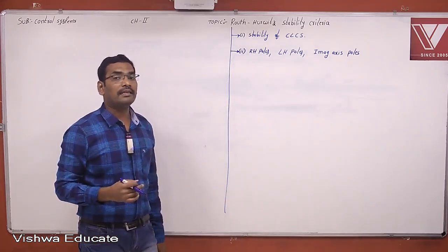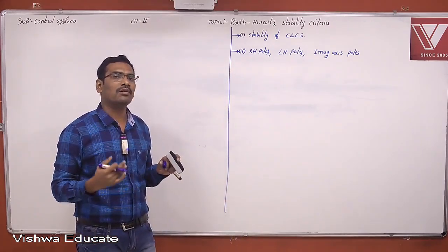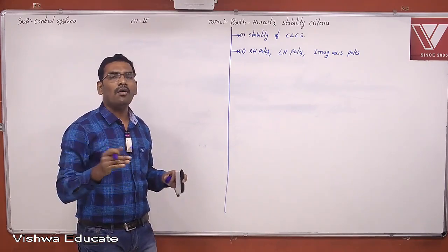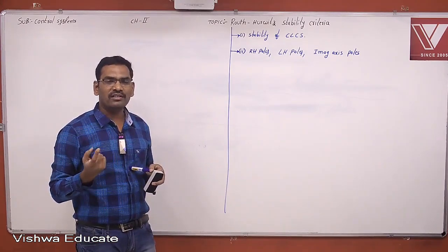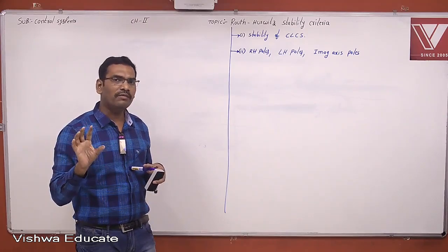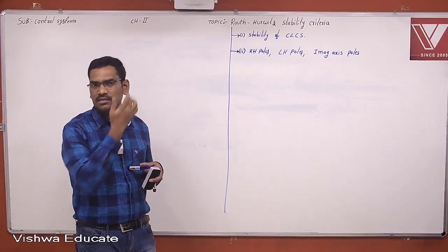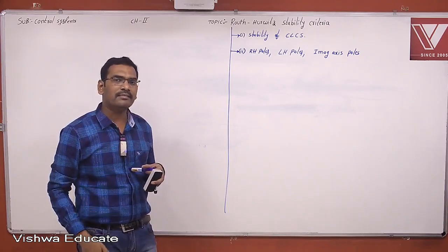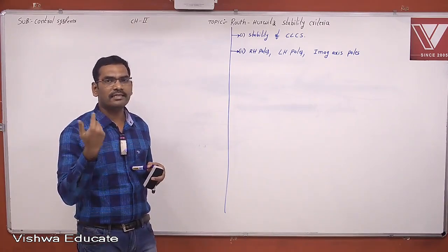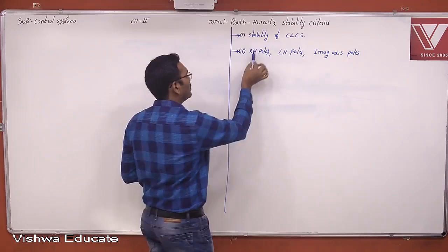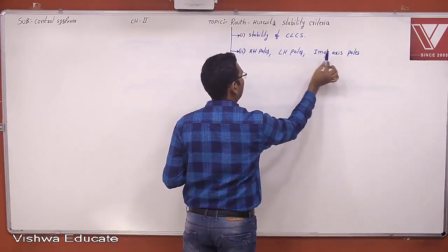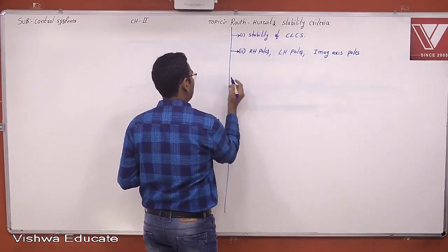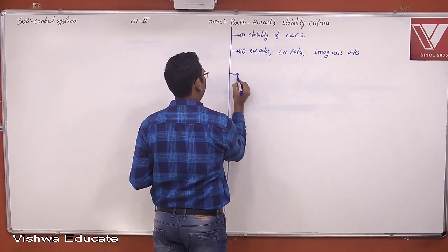Now the RH criteria finds the number of poles on the right hand side, left hand side, and imaginary axis. Sir, if you know how many poles are on the right hand side, you have confidence, and the answer is very simple. If even one pole is on the right hand side, the system is unstable. So this RH criteria is used to find the number of poles on the right hand side, left hand side, or imaginary axis. That is another feature of the RH criteria.